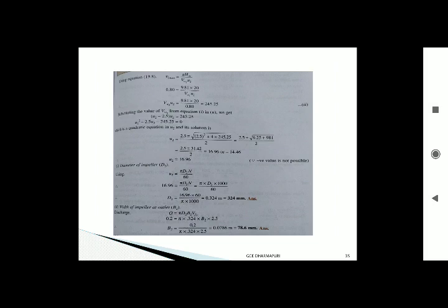For discharge, I know the formula pi d2 b2 Vf2. Vf2 is also given. The only thing not known is b2. D2 we found in the last step. If we substitute everything, we will get b2 in meter. We convert that into millimeter.